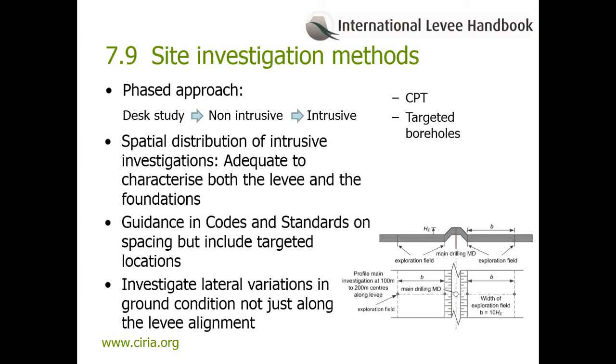Because of their linear nature, intrusive investigations are often undertaken only along the line of the levee, but soils will also vary laterally across the levee. An investigation should be undertaken offline, as illustrated in the figure.